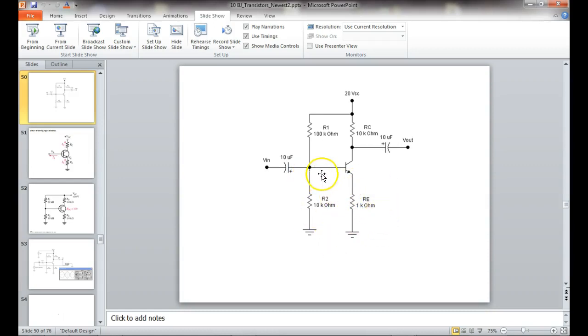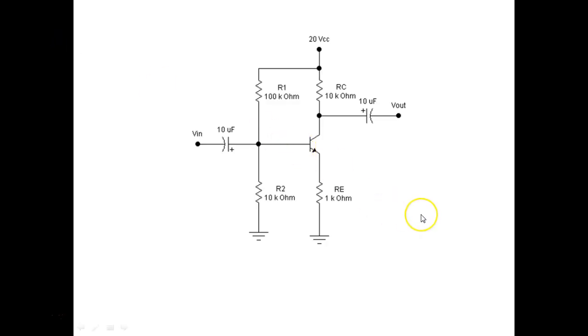So what happens if we clamp the base at a certain voltage, and here what would that voltage be? So we just come up here and do what? Just use the voltage divider formula real fast, right? This is the guy that's setting the bias on the base right here. So all we're going to do is calculate VB, all we do is calculate the voltage drop across that resistor.